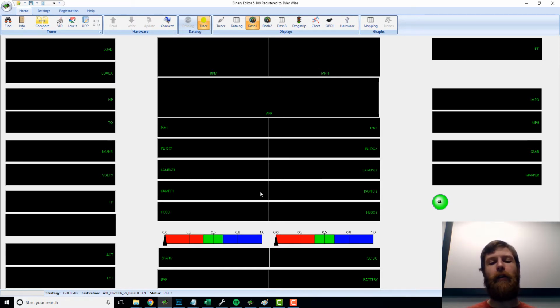As it adjusts, it'll move slowly. It'll go from 1.0, and then it'll drop a little bit, and drop a little bit, probably in little 0.01 increments. And then eventually it will stabilize and it'll stop moving, and that's when it's adjusted far enough to believe that it's okay. Now, it'll only adjust so far in the tune also, and you can adjust in your tune how far it's allowed to adapt, but by default, it's only going to adapt about 12% up or down from whatever the tune says it should do.